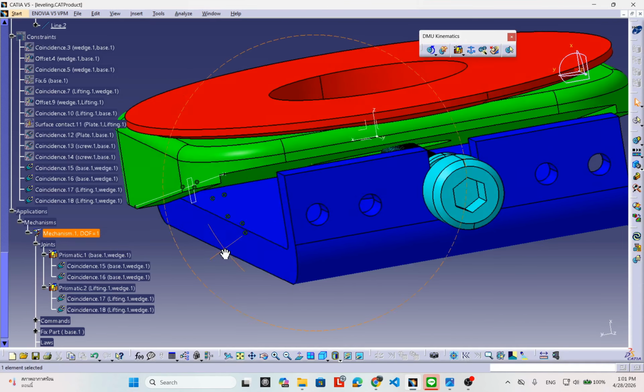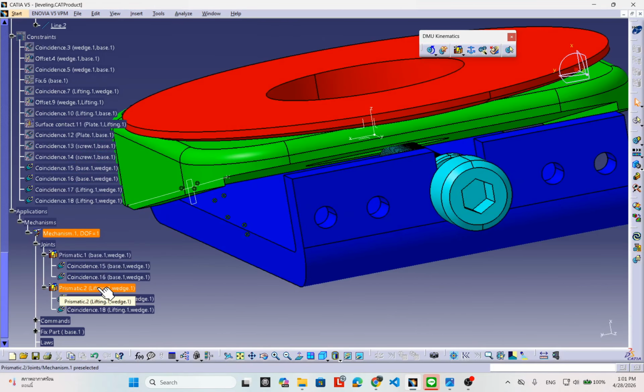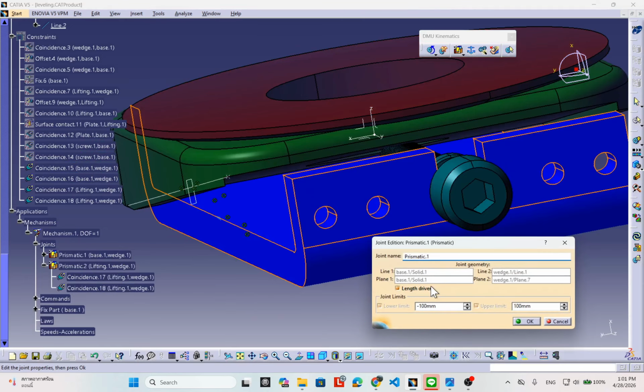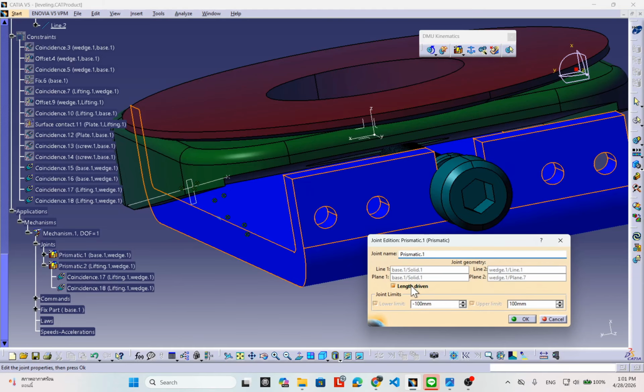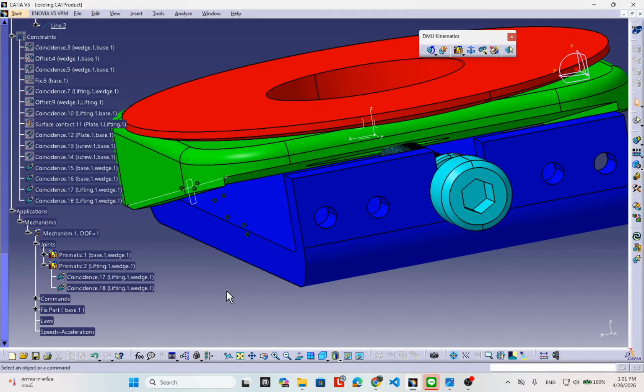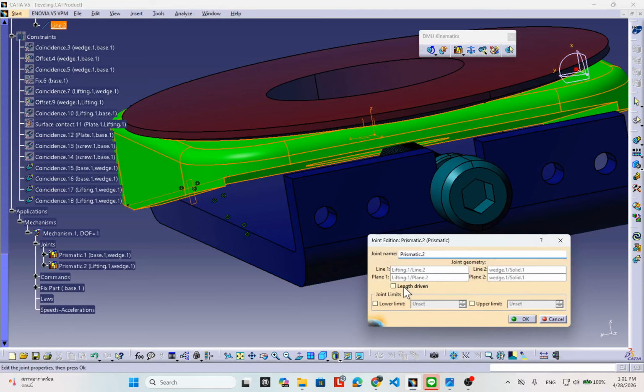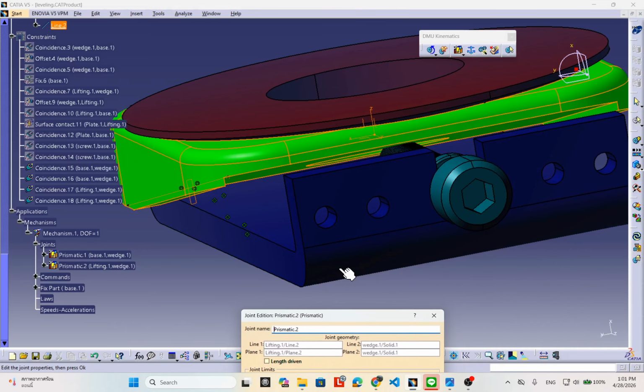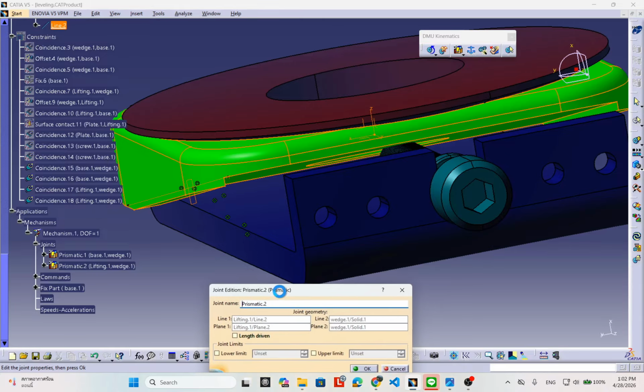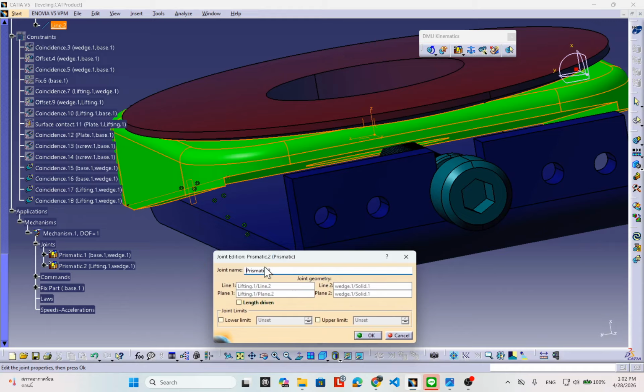Right? Okay, you need to assign that because it's one driver. Driver number one, I set up a driver, the linear driver, right? And if you set up here, we come to driver again. That means you're going to have the motor and linear driver, right? The actuator. You drive one prismatic joint. You drive by the external force, right? And if you drive it again, because you need to complete it, degree of freedom zero, right? Because the left is one degree of freedom, not completed that side, right?